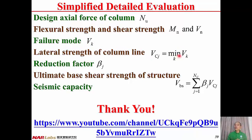That's the failure mode to be realized, and the minimum one is assigned to be the lateral strength of the column line. And according to the failure mode, we can have the reduction factor for the lateral strength of the column line, beta J. Once we have the lateral strength of all column lines and the corresponding reduction factor, then we can have the ultimate base shear strength of the structure, VBS, equal to summation from J equal to 1 to NC, beta J times VCJ, and that is the seismic capacity by using simplified detail evaluation.